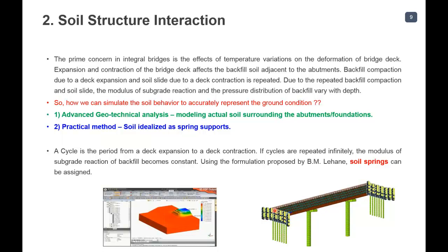To model this and to take care of this soil behavior, generally we have two approaches. One is advanced geotechnical analysis, where you can model the actual soil surrounding the abutments and the foundation, something like this, in a particular finite element soil program like our MIDAS GTS, which is geotechnical software.